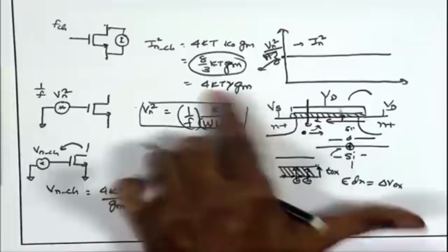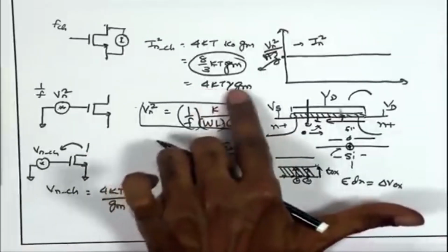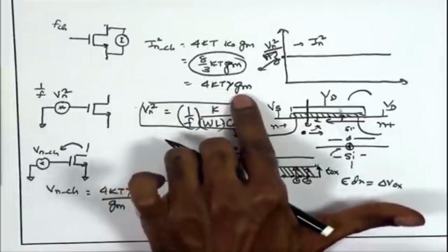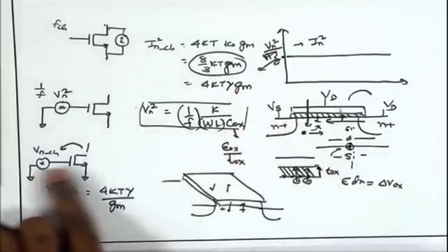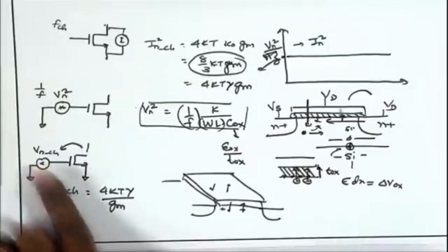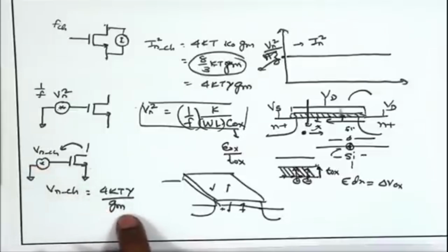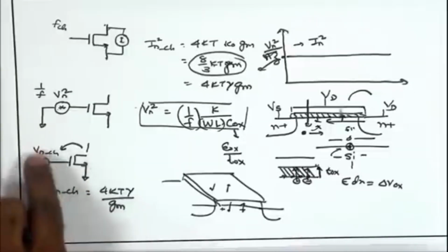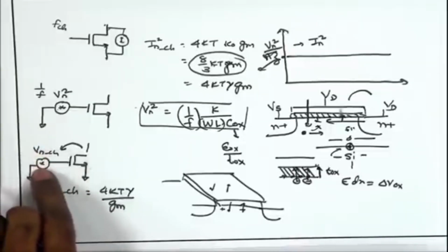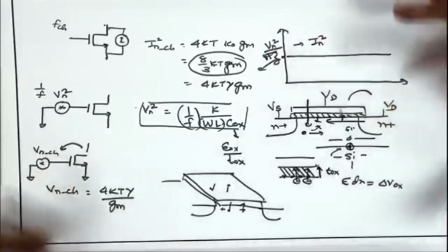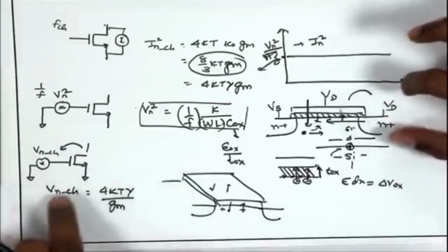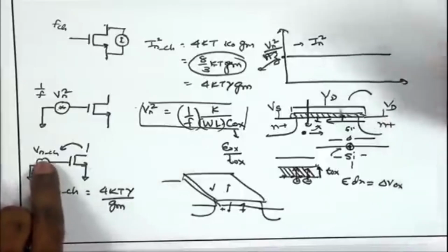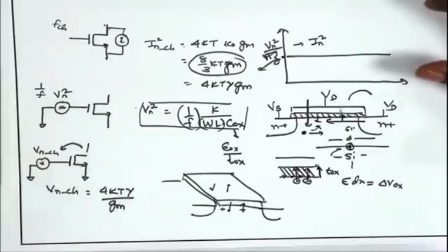Therefore, although it may look like the channel current noise is 4 kT gamma gm and creating a larger gm may mess up my noise, in fact, if I refer it back to the input and compare it with the input signal, then not really; a larger gm may help to reduce the input referred noise at the gate. That is another very important concept while dealing with more complicated circuits where you have a bunch of transistors inside the circuit. We try to derive the equivalent input referred noise of that circuit, so that it can be compared with the input signal.